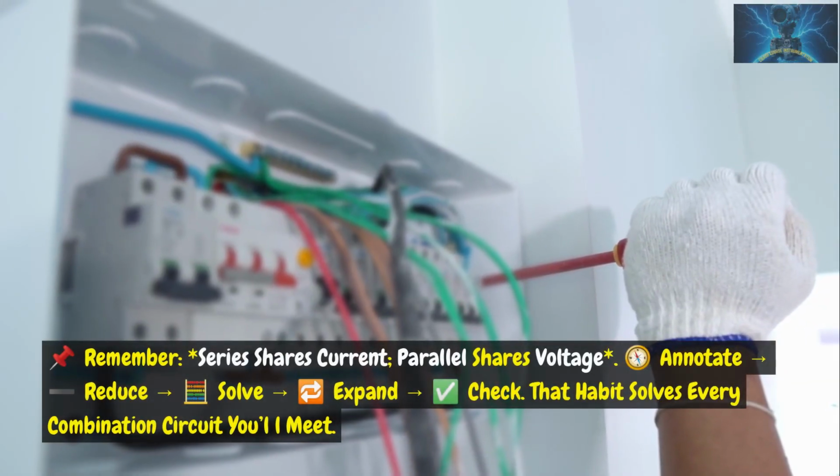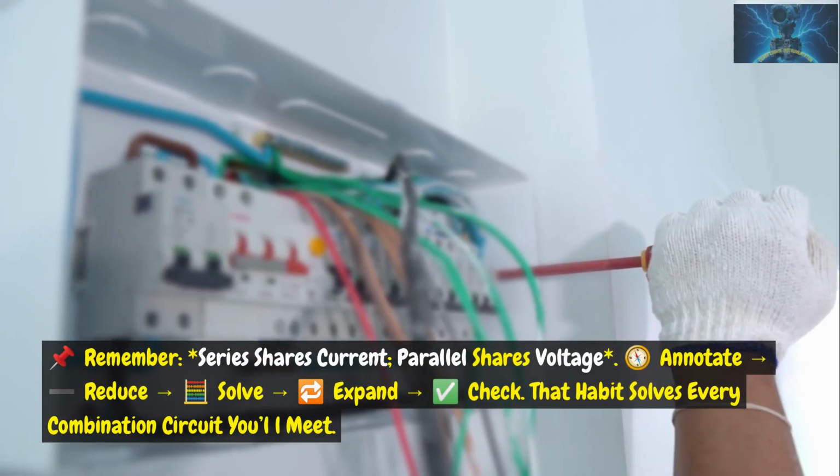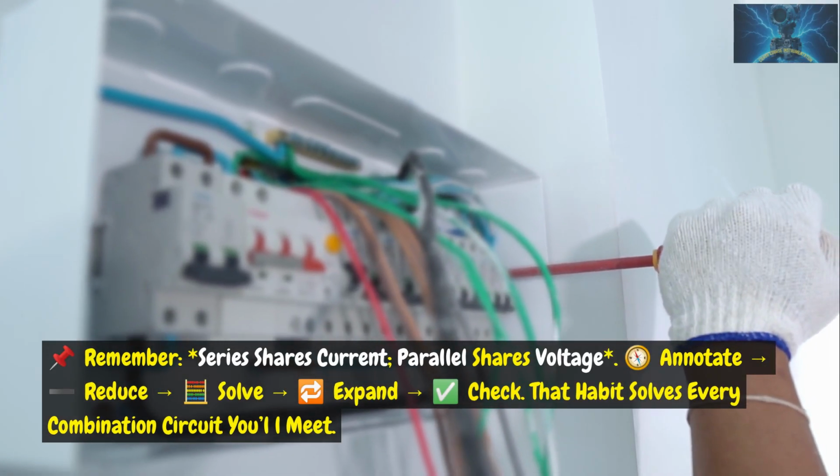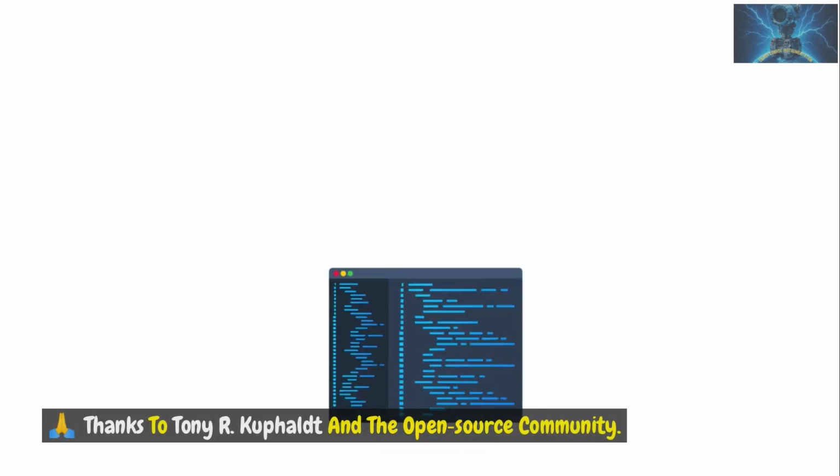Wrap and next steps. Remember, series shares current, parallel shares voltage. Annotate, reduce, solve, expand, check. That habit solves every combination circuit you'll meet.